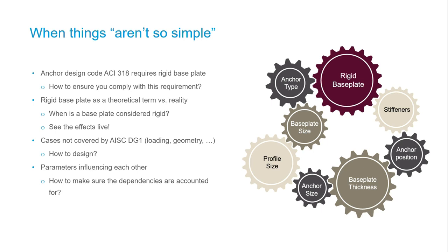That's what we did. First we started off and said, okay, what might be the implications? And this is what I want to demonstrate to you here. If you assume a rigid base plate and you compress it, the stress distribution underneath your base plate will be constant. Everywhere the same stress. If you now assume your base plate is not rigid, if I push here, you will probably see that underneath the profile, and as an engineer, it makes sense, right? Underneath the profile, you have higher stresses, and at the corner of the profile, you have lower stresses. So if you just assume a rigid base plate, and your base plate is not rigid, you might underestimate some of the compression stresses. Okay, compression stresses, somebody could say, not too much of a big deal, because normally the concrete is anyhow not failing, so my gut feeling tells me it will work, right? The next thing is tension.